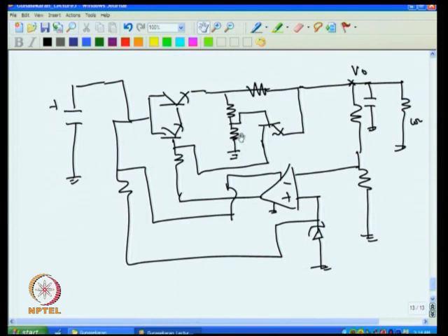That work is done by this, and that happens because of this voltage divider. This is a remarkable circuit because one need not unnecessarily over design the heat sink for the regulator because of this arrangement. This is actually classically called foldback current limiting.